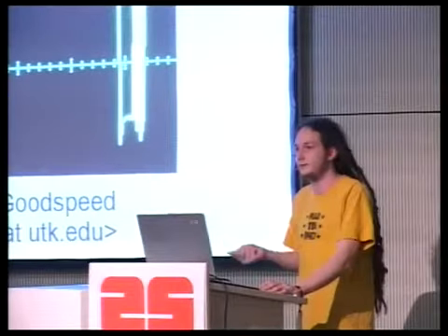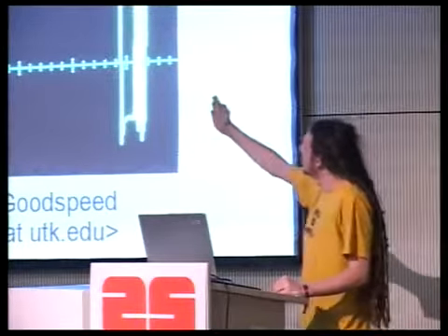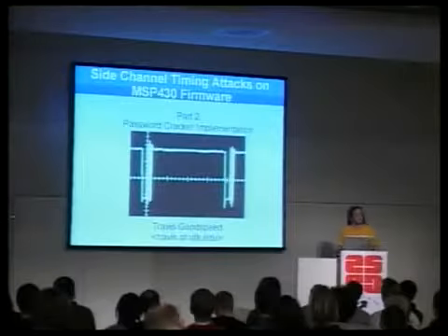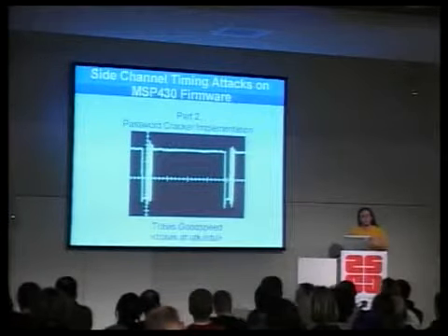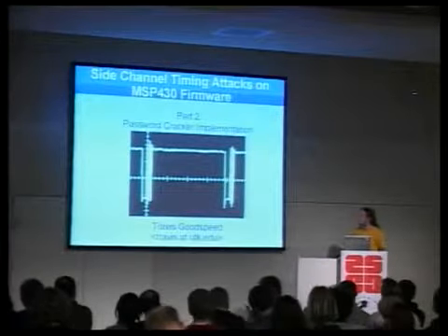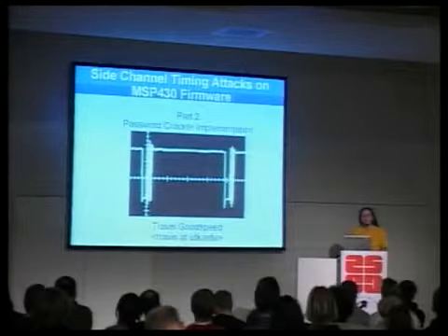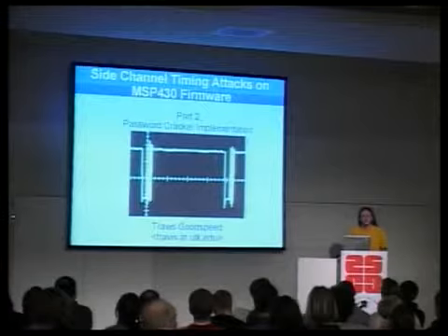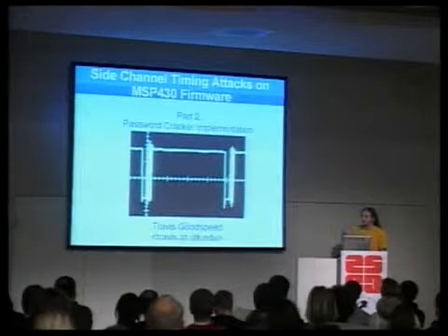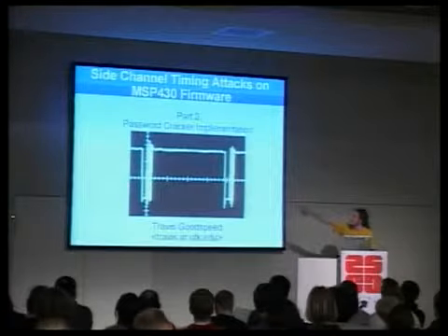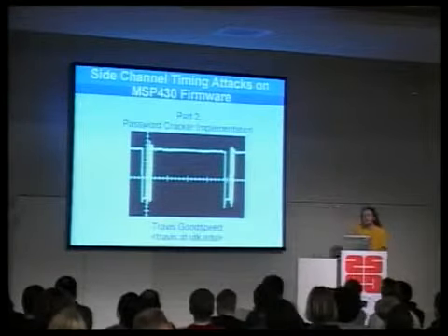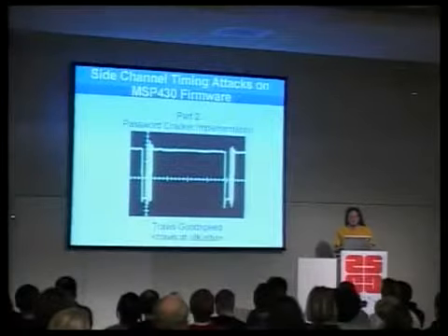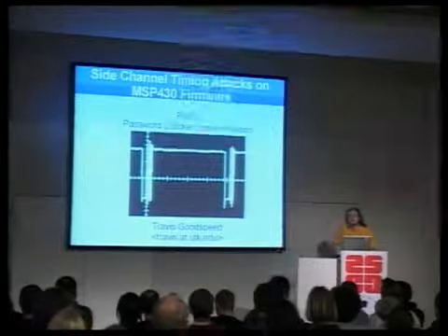The basis of the attack, though, is in the timing of a password comparison. If you look at this waveform on the title slide, the left is an acknowledgement telling the attacker that it's okay to transmit. Between the two signals, the attacker is giving a password guess, and he's doing it with non-standard serial timing. Then the right waveform is the victim telling the attacker that the password is wrong, and that he's not going to be given access to protected memory. By using non-standard timing, you can make it such that the only thing affecting the difference between these two waveforms, that's like the end of the first and the beginning of the second, is how correct the password guess is. And you can make this distance vary by 2 clock cycles per correct byte of your guess.